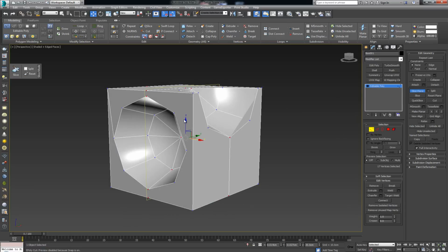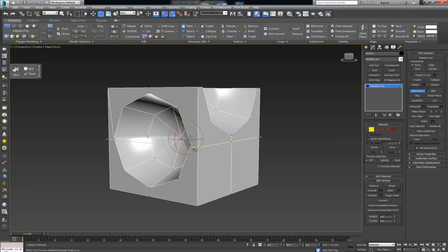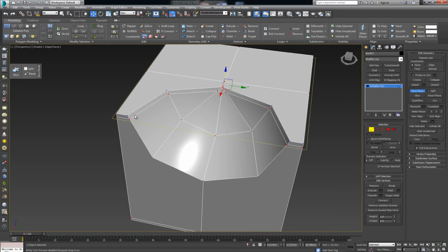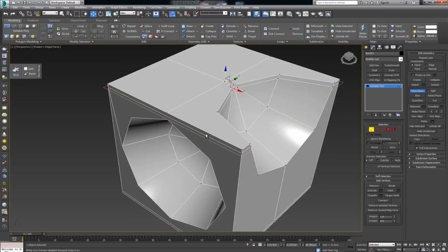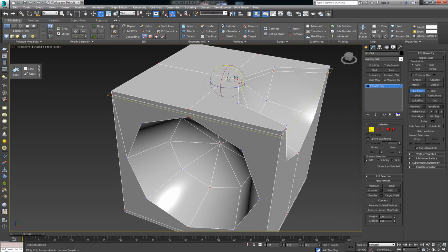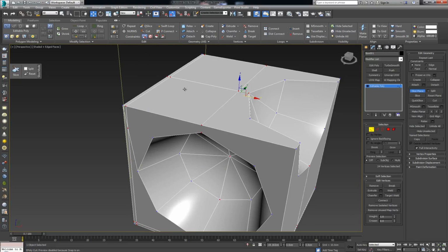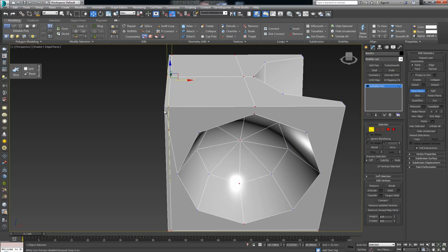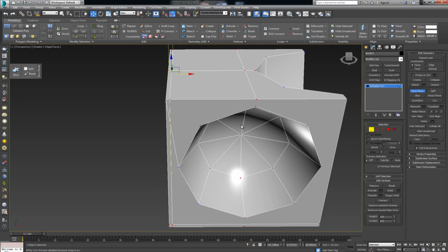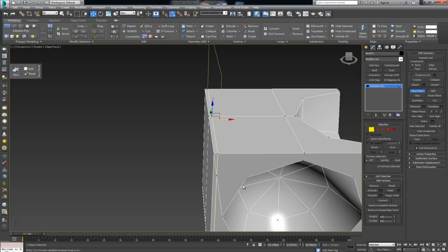And what we want to do here is, now we want to go ahead and do a few more slices on the edges of this box. So down here would go one slice. We would need to have one more here, but actually if I do it like this, it's going to give me this extra edge that I'm going to have to clean up later on. So I'm going to go with the cut and actually put that manually in. So I'm going to go like this. Again, 90 degrees, put it on this side. And this line is really not that important, as this is the way Max is trying to make heads and tails on how to deal with this n-gon in the middle of its polygon. So here, manually, let's just put in this slice.